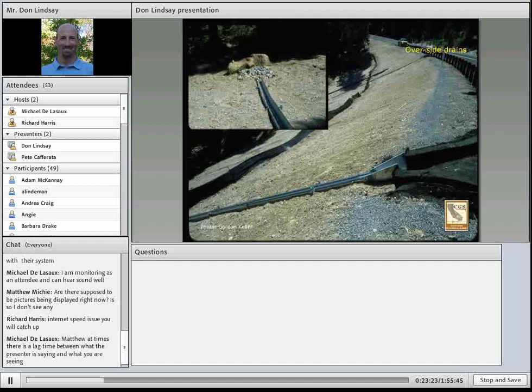Overside drains are generally used on crowned and outsloped roads where an outside berm is used. Typically, they consist of an inlet structure with a slope drain. In this case, the slope drain is composed of an open-topped flume. However, closed pipes can also be used. Notice how the flume is properly anchored down the fill slope. Outlet protection is also provided to dissipate the high energy flows exiting the flume. Overside drains can be effective and more cost efficient than traditional riprap if installed and maintained properly, particularly where the fill slope has a long slope length.